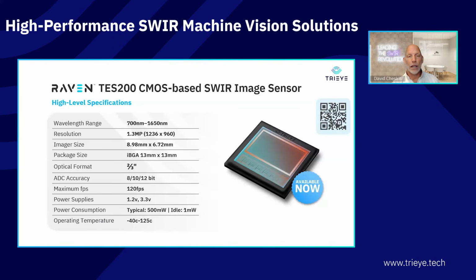And so what does that mean? Let's talk a little bit about what we've done with that. And so we've taken this Raven manufacturing platform. We've created a chip called the TES200, and that's our first CMOS-based image sensor. Again, because we've designed it to operate in the SWIR wavelength range, it goes all the way from 700 nanometers to 1650 nanometers. With the CMOS image sensor, we can get small pixels. We can do 1.3 megapixel resolution in a relatively small image sensor size, about 9 millimeters by 7 millimeters, and package it in a standard 13 millimeter IBGA package. So again, this looks like any other CMOS image sensor with the exception of the fact that it will work all the way through 1.6 microns.